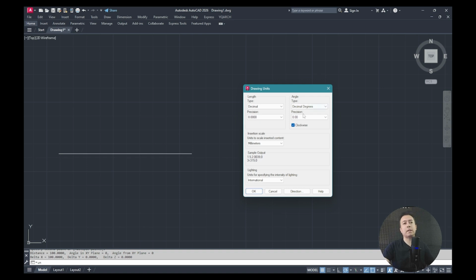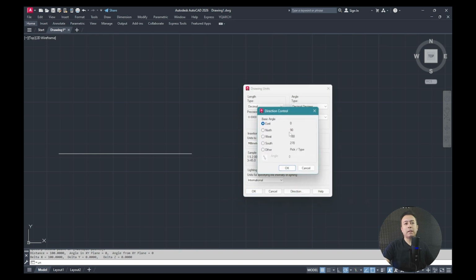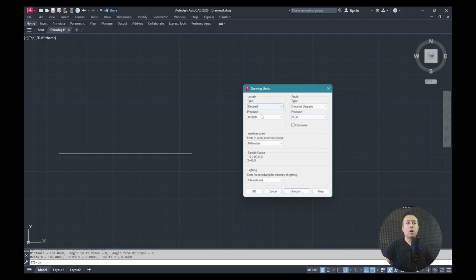So when I remove this, this was a summary of the topics related to setting the unit in the AutoCAD software. The last point is that if you click this option here, you can even tell it that this direction is not my zero line. For example, tell it that it is the perpendicular direction of my zero line. For example, from here, the zero line is this way or this way. You can rotate and adjust the angles. There is no need to do this at all. Well, all these settings were related to the AutoCAD software unit, the length and the angle.